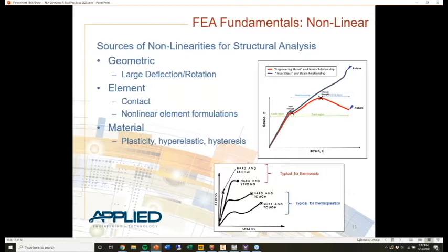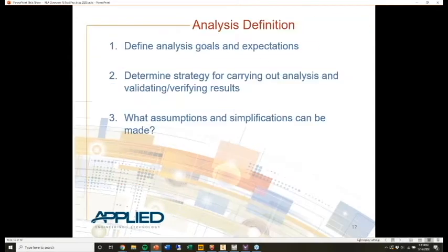And maybe the nonlinearity that we can most easily associate with would be our material nonlinearity. If we're dealing with plasticity in metals, or maybe different plastic materials or hyperelastic materials, we will have nonlinear material models, and again, our K matrix will become nonlinear. All of these lead to the need for an iterative solution process. If we have a nonlinear FEA model, we need to use an iterative solution process to solve it. We can no longer directly solve for the single unknown variable. We have to use the iterative solution process, which is basically a guess and check solution, okay? There's quite a bit more associated with doing that, and it can, from time to time, involve quite a bit of troubleshooting. If some of your things aren't quite working out how you thought they would, you might need to do some troubleshooting on your model.